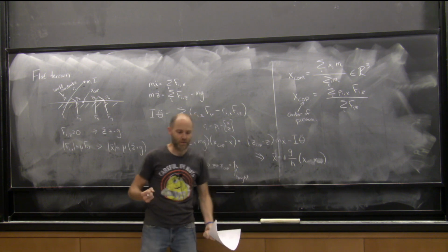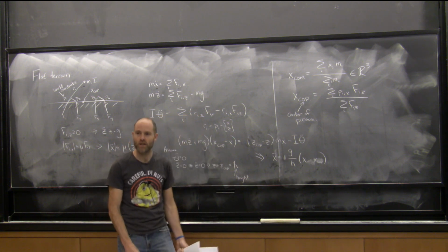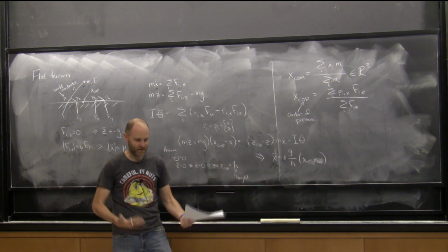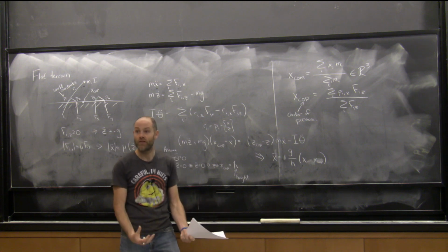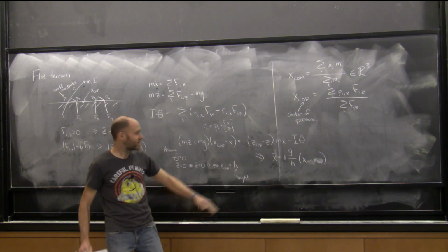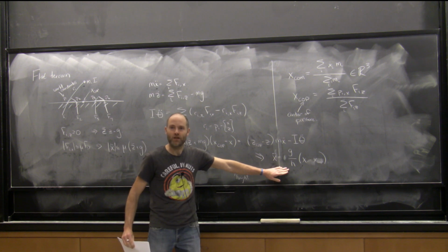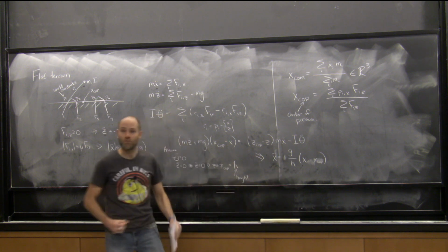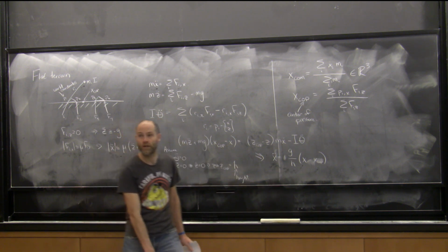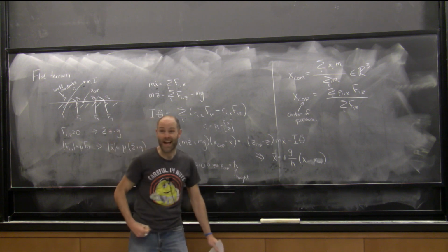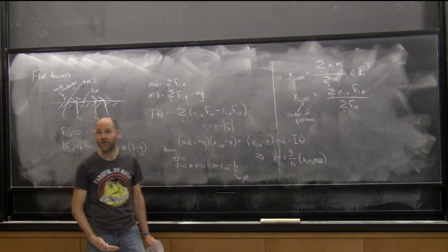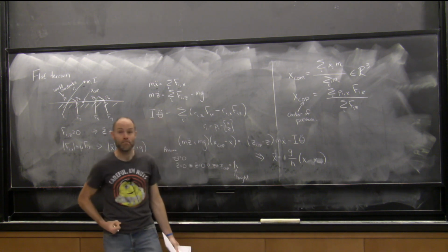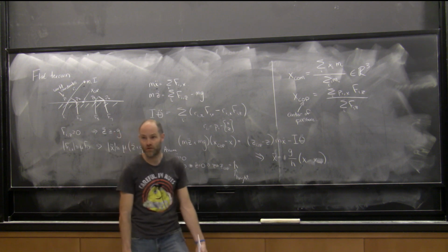The argument originally was, if you don't have torque control of your joints, how can you regulate the forces on the ground? The Neville Hogan view of the world is that you want to regulate your interaction forces. This equation says to me you can regulate your interaction forces even with a position-controlled robot. Because if you're moving your center of mass, you're actually controlling your ground reaction forces directly. Asimo's doing a great job of controlling its ground reaction forces. It's not by sensing force and closing some impedance control loop on that. It's by moving its center of mass around, which it can do, assuming that the feet are on the ground, and that's just kinematics.